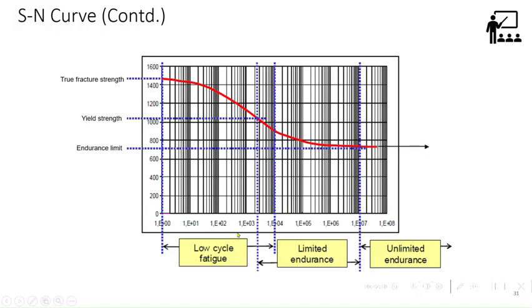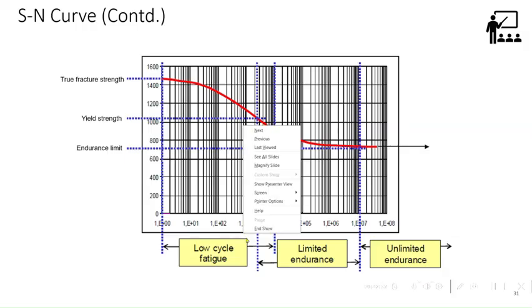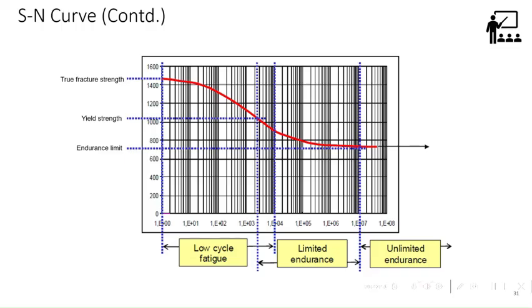So 1 to 10 to 3 is known as low cycle fatigue, where there is too much plasticity. So in aircraft structure, we don't consider any low cycle fatigue except for an engine. Even in an engine, some parts are analyzed for high cycle fatigue, low cycle because you have a high centrifugal force, then you have a temperature in turbine area, hot region, and all. Obviously, some of them will undergo plasticity, or even automobile, high ductile material. So those are low cycle. But in aircraft structure it is always high cycle fatigue, which is within elastic limit.